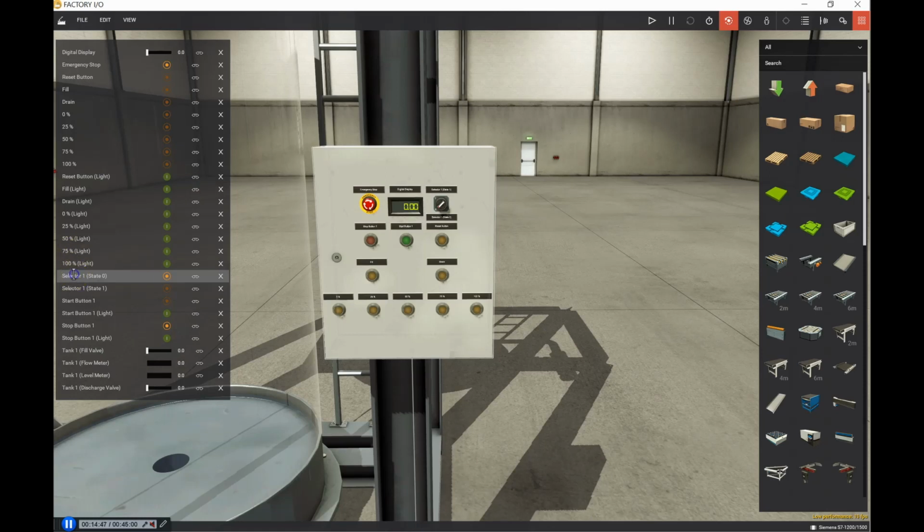So we're going to take this guy and delete everything. When you select auto, it's going to be like a normally open contact, and when you select the auto, it's going to change to a closed contact. The other portion of my selector switch is going to be a manual mode.